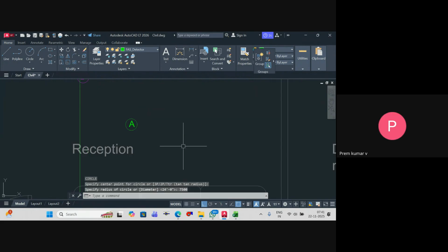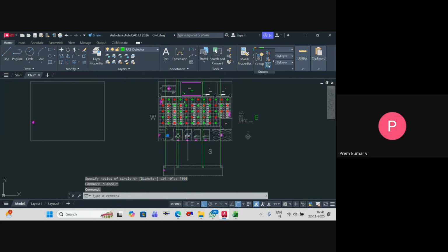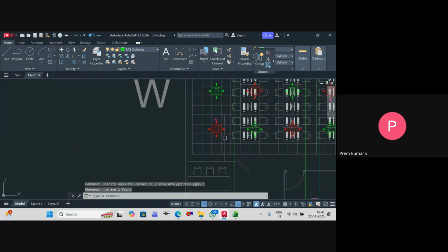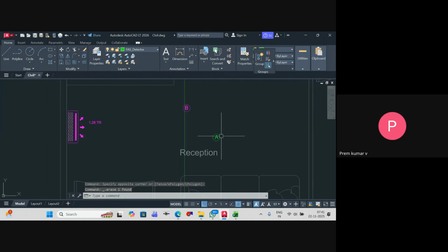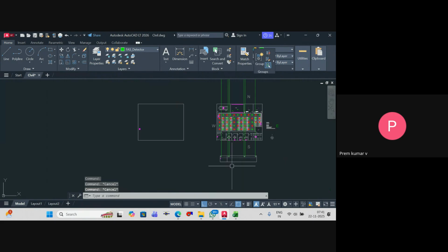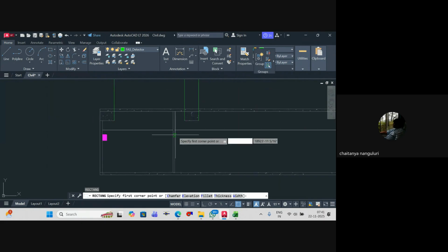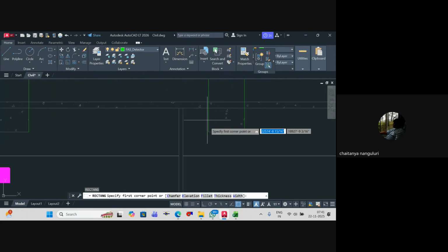Sir, we had one more condition there, where the partition wall is not greater than 300 mm. That one is if the partition is greater than 300. For beams, as I've said, if it is greater than 10%, you have to consider it as a separate zone.